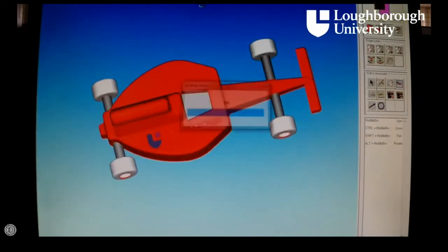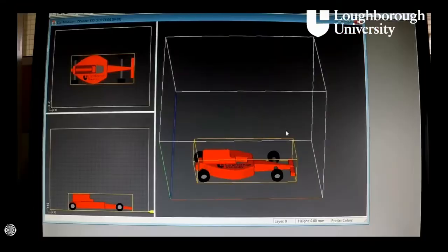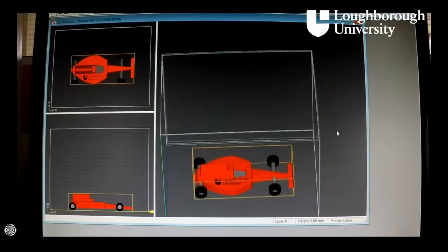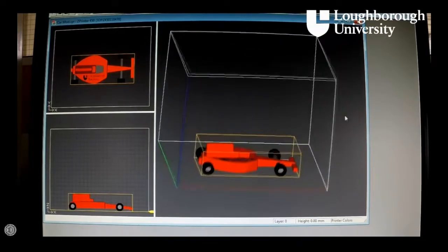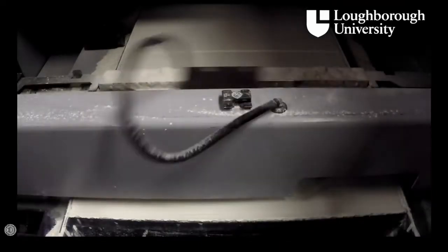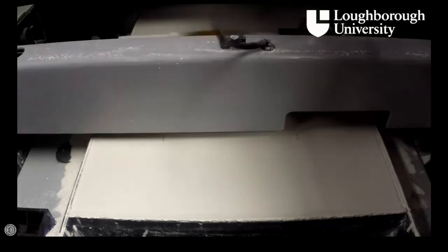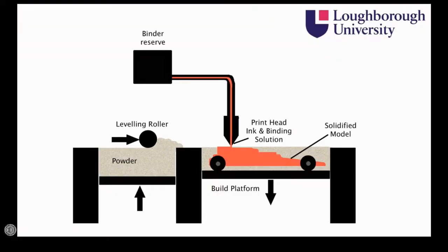The 3D process allows full-color models to be produced, providing an aesthetically pleasing finish. The build software slices the part into layers 0.089 mm in thickness and sends it to the printer. The roller spreads a layer of ZP130 plaster powder over the build platform. The printhead then moves across and prints a layer of binder solution infused with coloured ink in the shape of the first layer. This binder solution glues the powder together in the desired shape. Any excess powder left unbound acts as a support structure for the part, much like the SLS process.